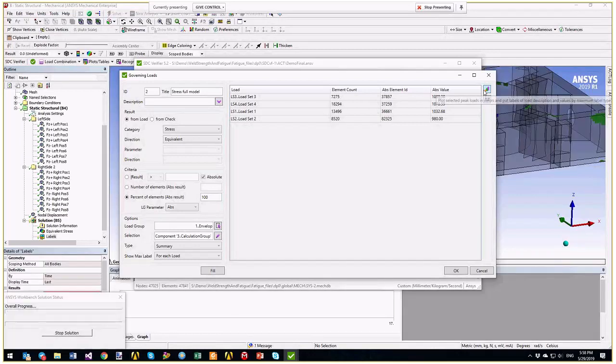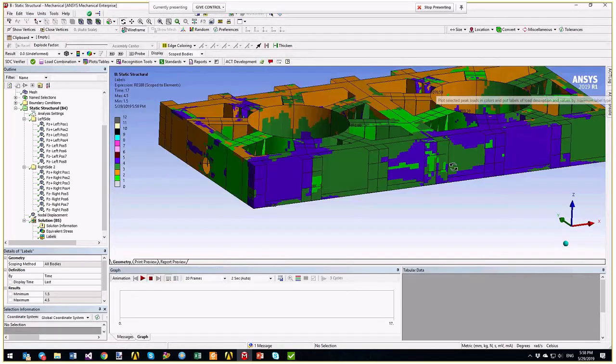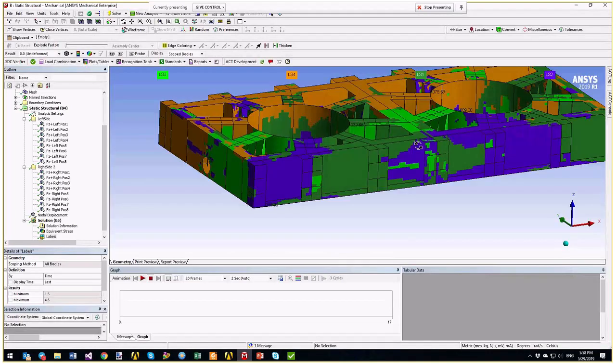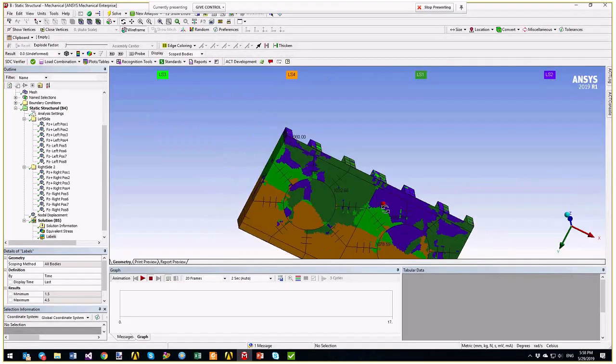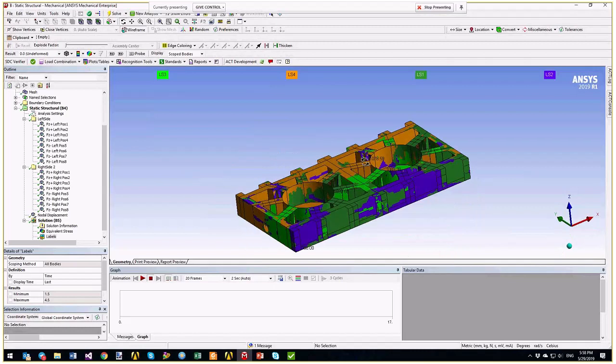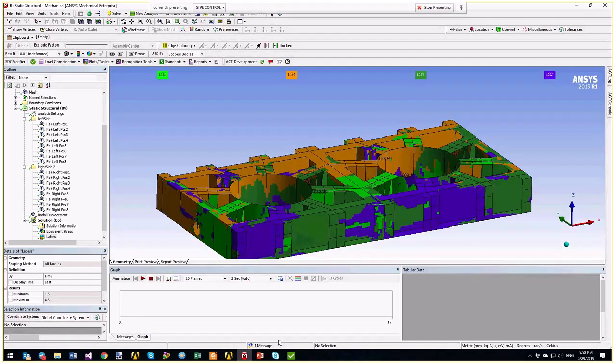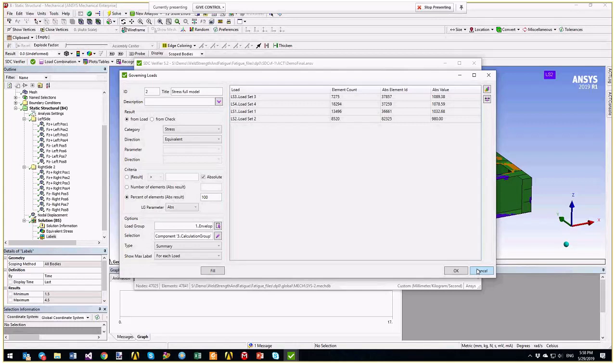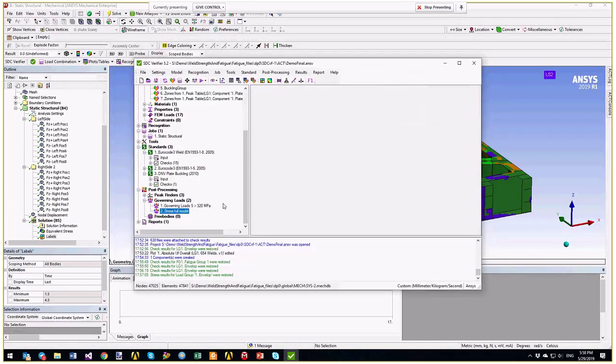Those tools, Peak Finder and Governing Loads, can also be included in the report. You can see the distribution of stresses from different loads. Okay, and finally, we needed 3 plots and 2 tools to make some estimation of our results in SDC. We did the setup in 20 minutes. If you know how to configure SDC, it's not that hard.